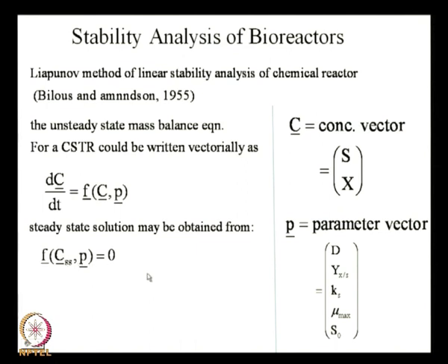Let me try and explain. What we are trying to do is not obtain the unsteady state solution of the problem. As I said, what we are trying to do is give a little perturbation to the system and see how the system functions. We are looking at how it functions in the vicinity, or the neighborhood, of the steady state. So, as soon as I say that, what rings a bell? I have the steady state and I am trying to look at what happens in the vicinity of the steady state.